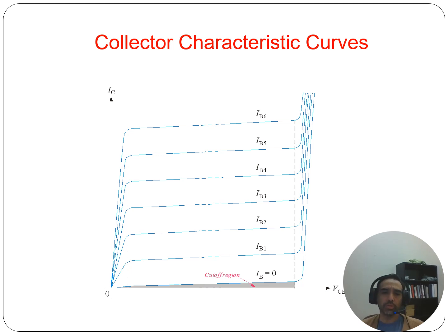So looking at this sheet, what do we see? We've got the horizontal axis, which is the x-axis, and the vertical axis, which is the y-axis. The x-axis shows the collector emitter voltage, VCE. The y-axis shows the collector current. So we have voltage to current here. Interesting. It's just a relationship between voltage and current, not like what you're used to seeing, a time to some amplitude.